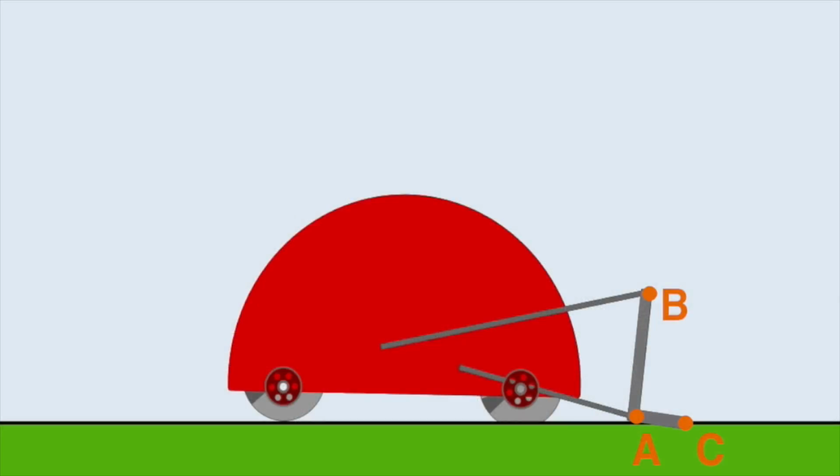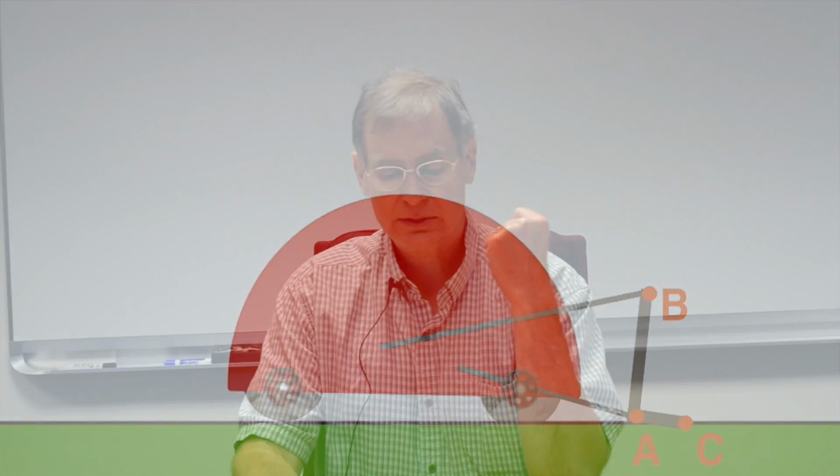So, with regard to the reference frame on the robot, there are 3 possibilities in planar motion. You could have a body that just rotates, so it's fixed. It has some fixed pivot point, and it only rotates about that point. Or you could have a slider mechanism that only translates, doesn't rotate, only translates. Or the coupler, in general, has complex motion. It both rotates and translates. So first, let's talk about how to determine the velocity on any point on a body that's rotating.